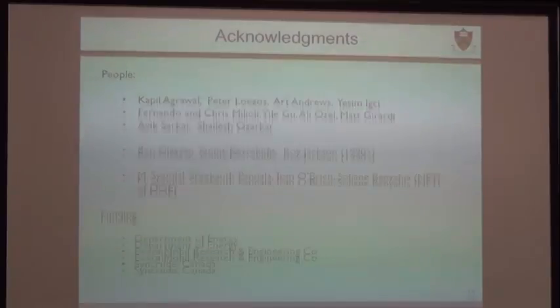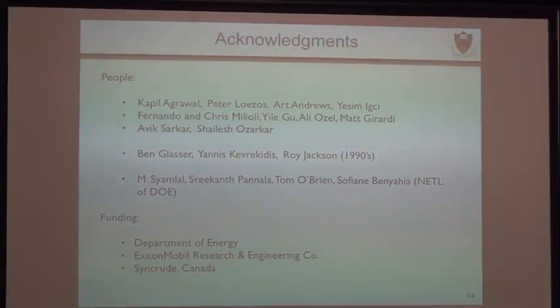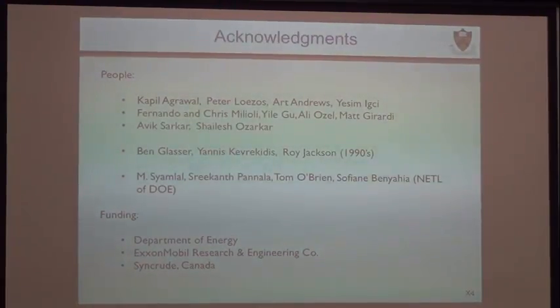There are different incarnations of drag laws for the fluid. When you use one of them, Gidaspow is one of them, then Beetstra is one of them. If you look at them, they have slight differences, but they all have the same qualitative behavior. So whichever one you use will give you the same kind of bifurcation diagram, same kind of instability and scale. It is not because of the drag law we are using.